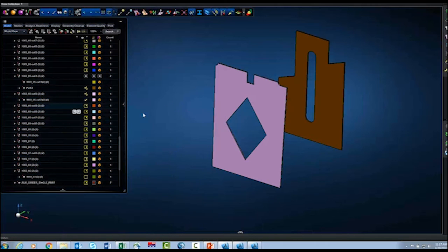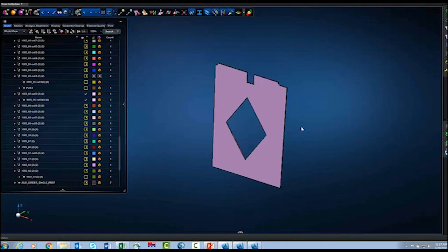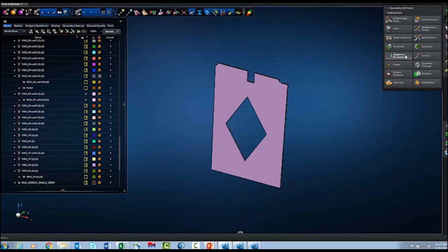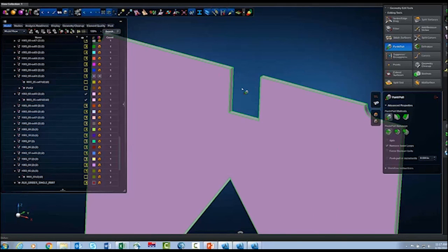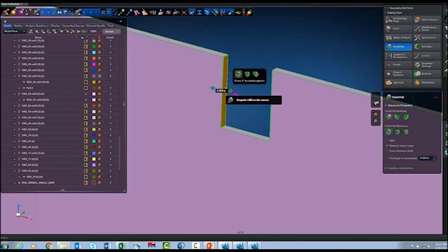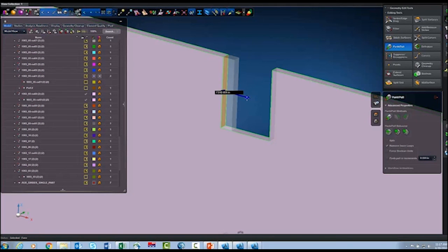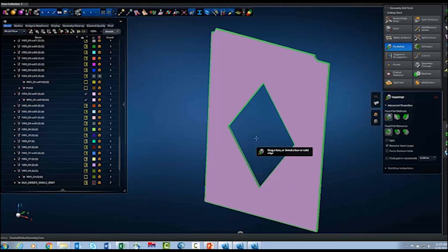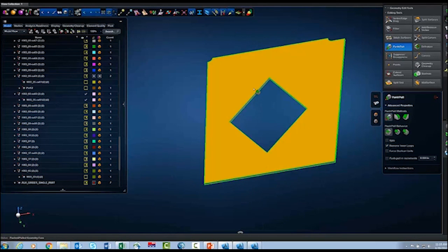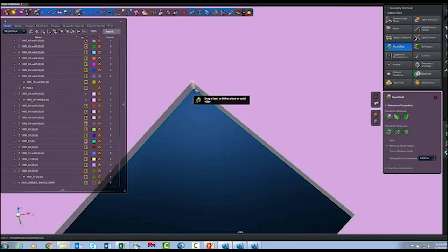Let's first look at this one here. We'll show it only. And I want to introduce you to some tools that we have for working with the geometry. The first tool is designed to work with solids. We call it the push-pull tool, and I want to close this gap. It does exactly what the tool says. I'm just going to grab a face, push it, and pull it to close up that gap. That might be something you would want to do in a model like this, because you might not want such a fine mesh to capture that level of detail. Maybe you're looking to do a loads representation of your model as opposed to a detail representation.